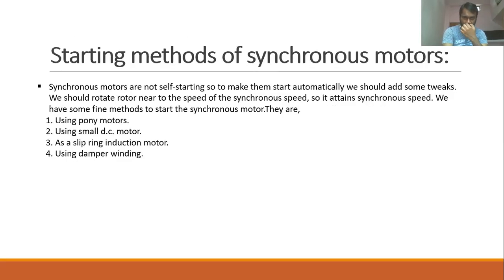Next one is the starting methods of the synchronous motor. As we already discussed, a synchronous motor is not a self-starting motor, so we use certain external methods to start it. We discussed this in short; we will try to discuss these topics in detail. We normally use four starting methods: using pony motors, using DC motors, using slip ring induction motors, and damper bars.